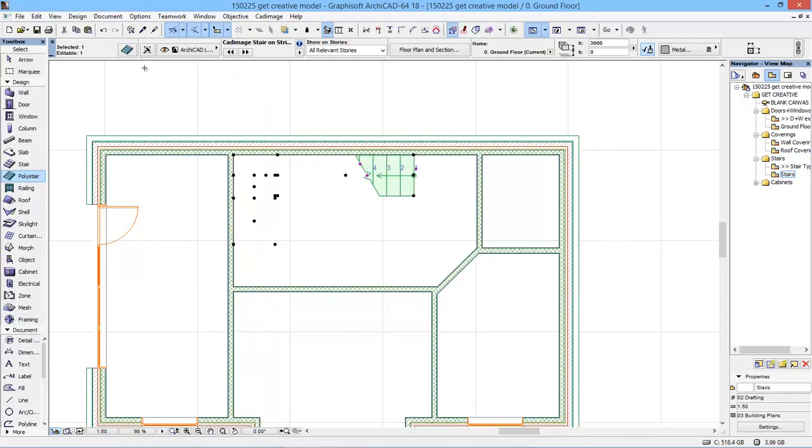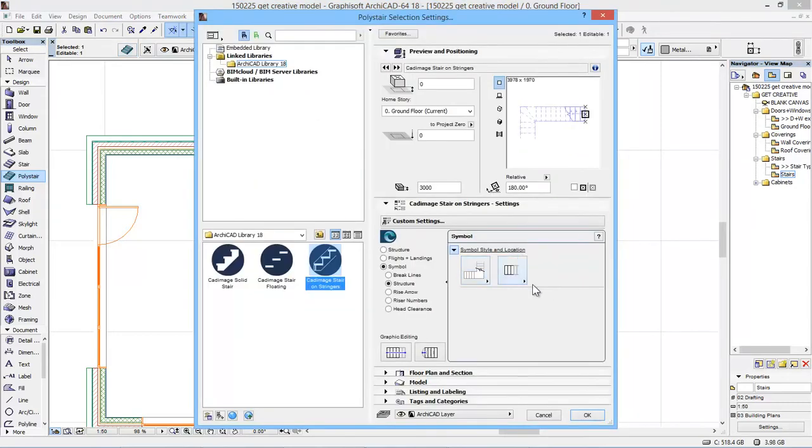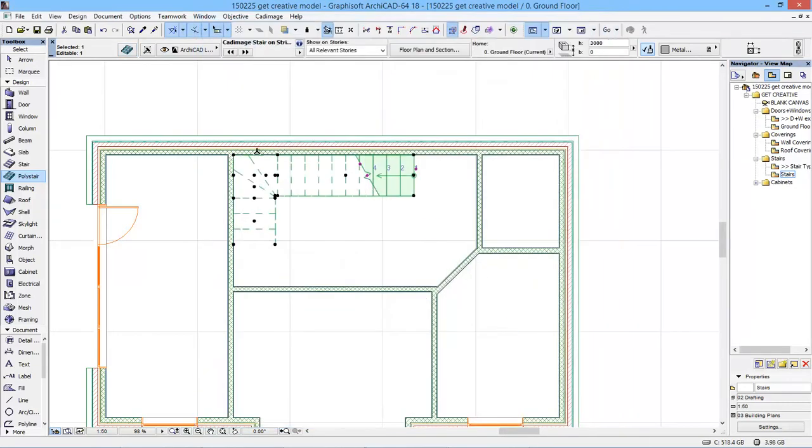So it then calculates. A couple of issues. We need to set the treads beyond so you can actually see them, and we can move this up and down. But what you'll see is it's created a straight flight and then 3 nice symmetrical kites, and then onto the last piece up onto the floor above.